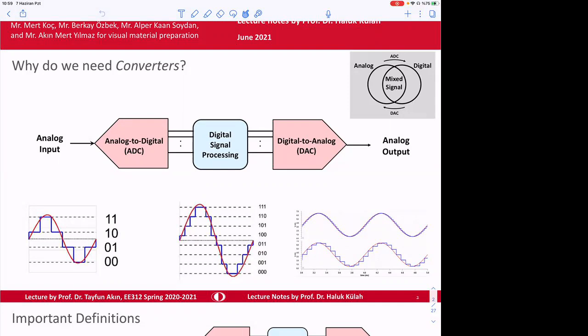And when we reconstruct that in the analog output, for example, in the analog domain, this is not going to be really good, nicely representing our signal, but it is going to be roughly representing. And then maybe we can do some filters and get rid of those sharp transitions, and get the signal again close to sine wave, but there's going to be loss of signal.